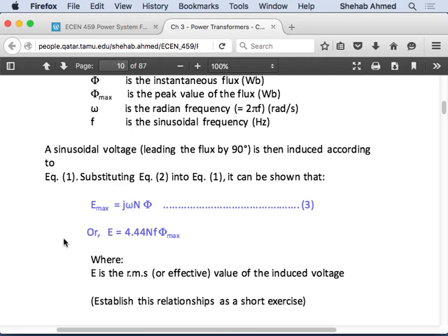That way you're able to increase the frequency, instead of 50 hertz, to 100 kilohertz. Can you imagine, if you're able to increase it to 100 kilohertz, the number of turns you would need is a lot less to operate at the same voltage? So you can live with a much smaller transformer. People are proposing that as a way to upgrade substations.